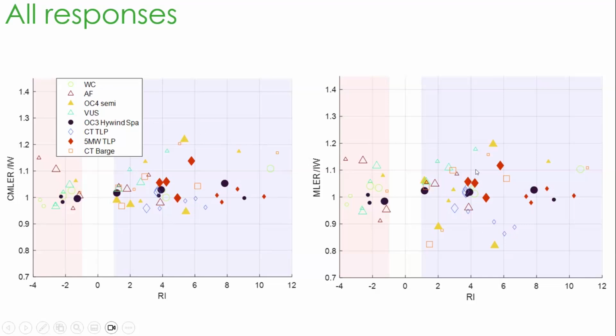And then for the single event, it's a bit wider. Part of this is because some of these lower cases are for the mooring load, and we wouldn't necessarily expect a single event to be able to produce the extreme mooring load, because the background wave is important. So a single focus wave on its own, we wouldn't expect it to be able to produce the extreme.